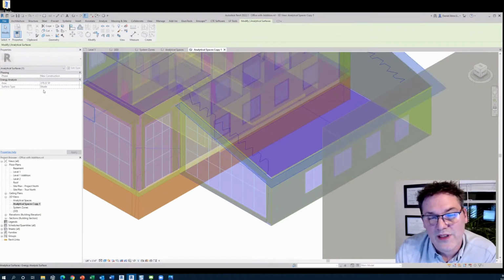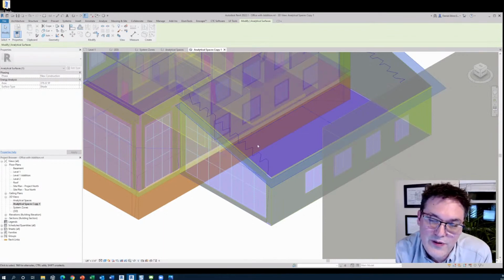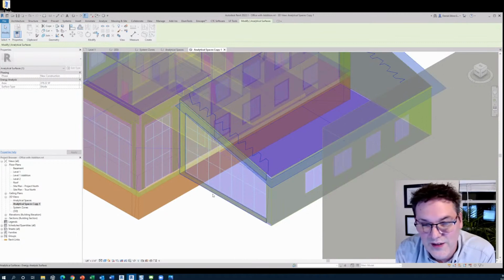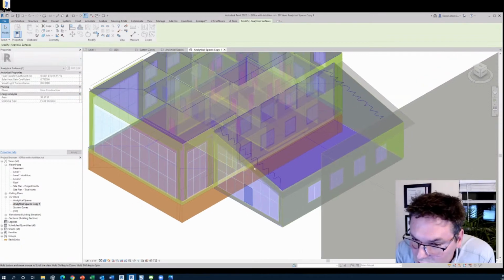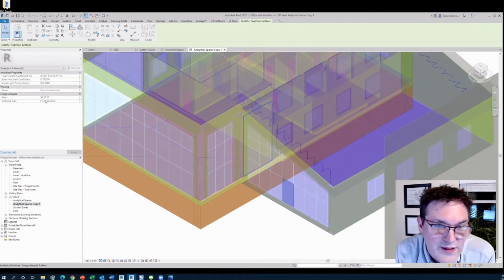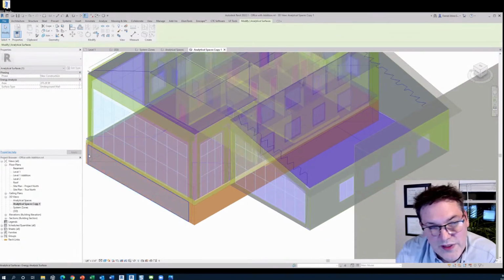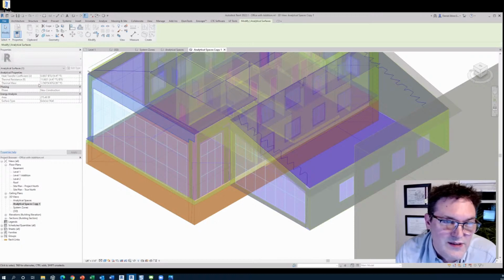So it's not relevant in terms of an EUI or thermal transmission, but the rest of that roof is relevant for blocking solar heat gain, for example. And there's glass here that showed up, and if we pick this wall, see it's an interior wall, and this exterior wall got broken up into underground wall. The parapet is a shade surface. The exterior wall has an R value.